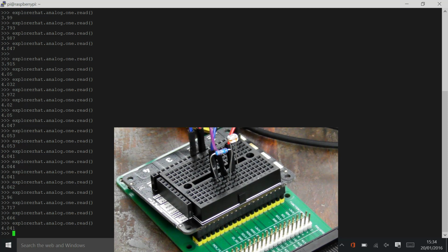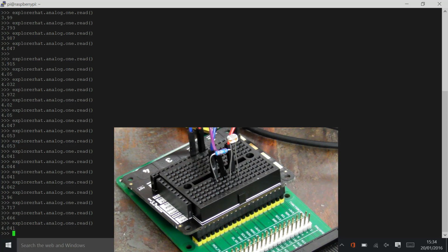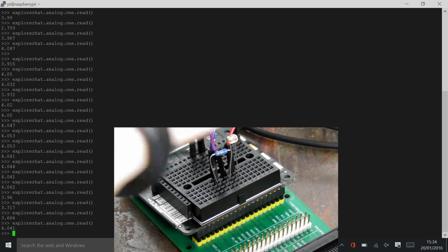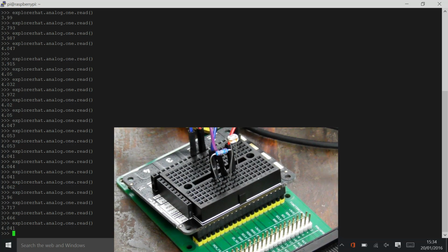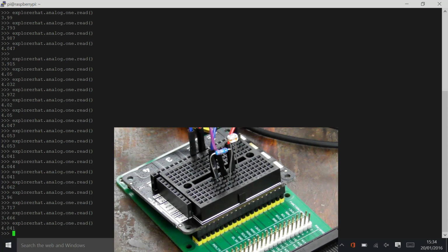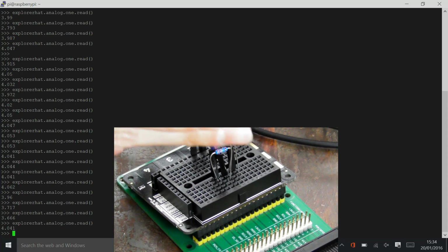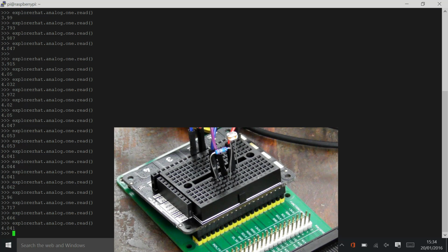And it's that changing resistance in combination with the fixed resistance that lets you actually tap off a meaningful signal. Effectively creating a voltage divider with one half of the voltage divider being variable. Yeah, exactly that. Normally part of the spec of this sensor would be that it's 10k, so you'd probably match it with a 10k resistor, so it's a reasonable choice. Then you'll get a decent range out of the readings at that point.